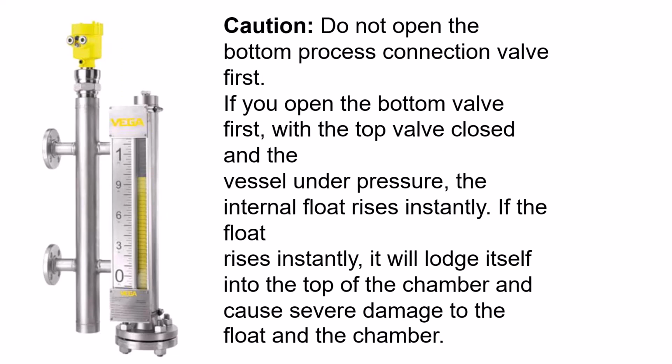Caution! Do not open the bottom process connection valve first. If you open the bottom valve first, with the top valve closed and the vessel under pressure, the internal float rises instantly. If the float rises instantly, it will lodge itself into the top of the chamber and cause severe damage to the float and the chamber.